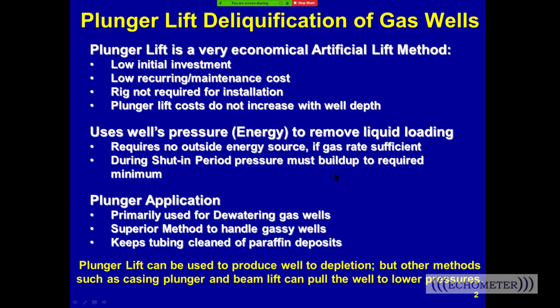Plunger lift is a method that's used to typically deliquify gas wells, and it's probably the most economical lift method because the cost to set the equipment up is low. The cost to maintain the equipment is low. You don't have to use a rig to install it typically.